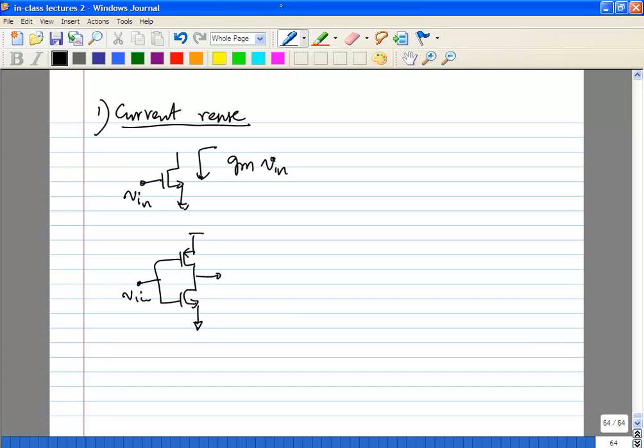If you take a single transistor, the transconductance of that is Gm times Vn for a given current. Instead of having a single NMOS common source, you can make it more like a common NMOS PMOS common source amplifier. So the total output current is Gm1 plus Gm2 times Vn. This is to get more gain for a given current. There are multiple ways to do it. This is just a very simple example. You can choose to implement something like this for your LNA.